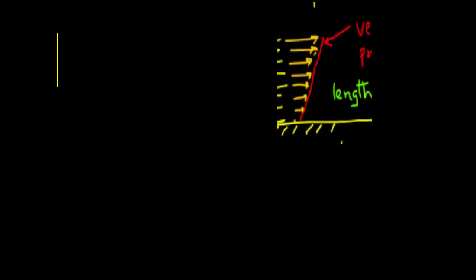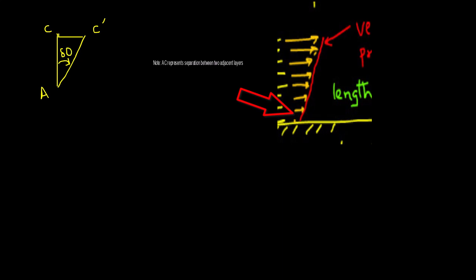In this velocity profile, we will expand this to develop a mathematical relationship. So we have the vertical line here expressed as AC, and after application of the shearing force, let's say that point C moves to point C dash. In other words, it moves by a distance delta x. And so the vertical line AC is now deflected to AC dash, and that angle of deflection is delta theta. And also, let's say that the distance between A and C is dy.